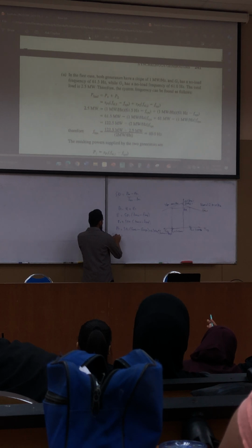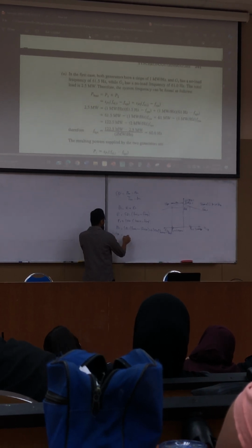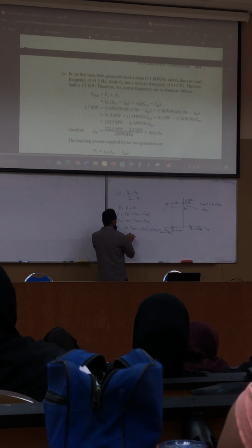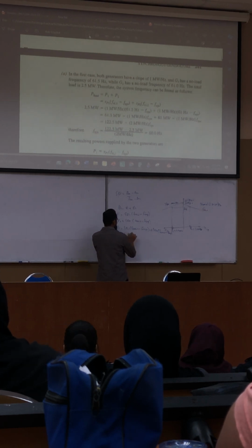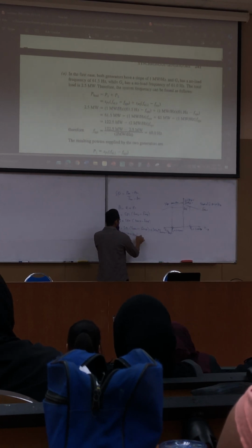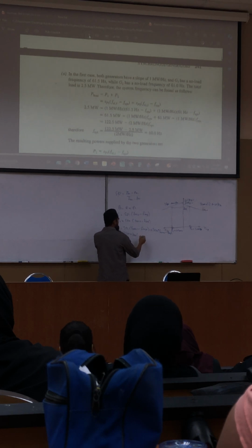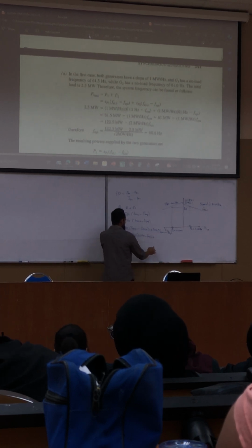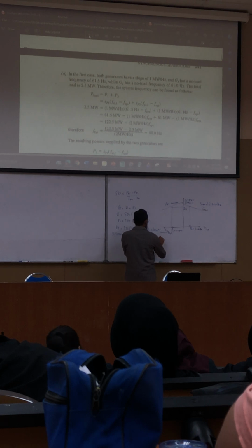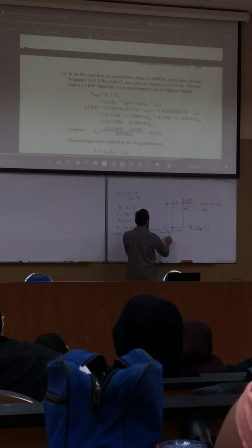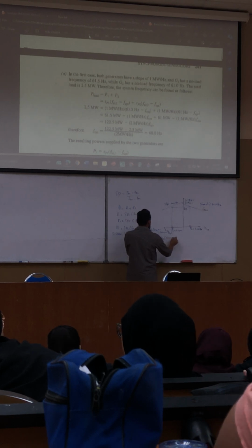You put in the values: 2.5 megawatt, speed drop 1, 1.2 megawatt per hertz, the first no load frequency 60 hertz, system frequency, speed drop number 2 is 1 megawatt per hertz. The second frequency is 61.5.